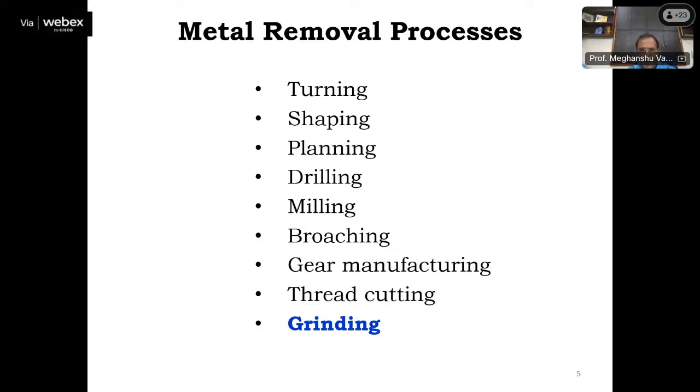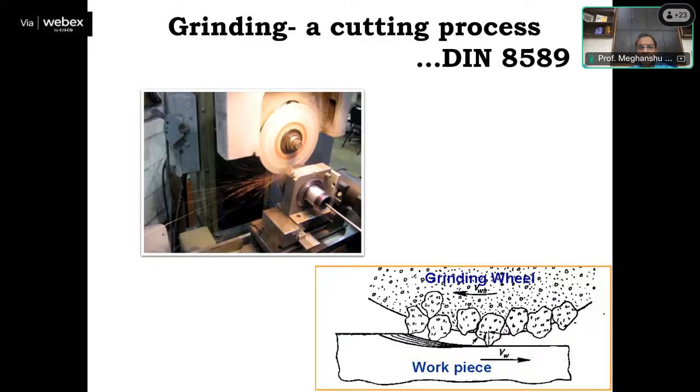To explain this technique in an easy way, I have again selected the same process. In grinding, abrasive grits act as cutting tools, and these grits have a large negative rake angle. Because of that, large cutting forces are generated, which generate enormous heat in the form of sparks, or chingari. These sparks occur only in the grinding process.